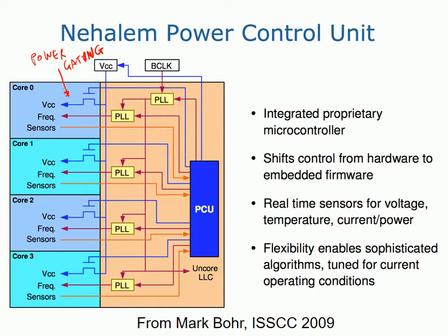Sometimes when the load is not really high, you can really switch off some of the cores, and the great advantage in switching off the cores is that you suppress completely the static power consumption, which is a significant percentage of the whole power consumption. Okay. If you go slow, you only reduce the active power consumption, the dynamic power consumption. In order to completely suppress the static power consumption, you need to switch the core off.